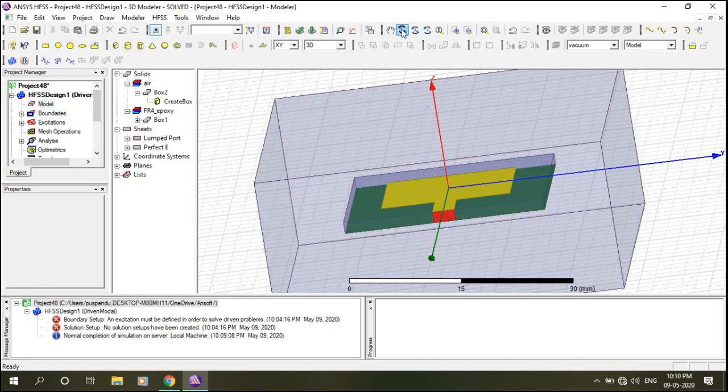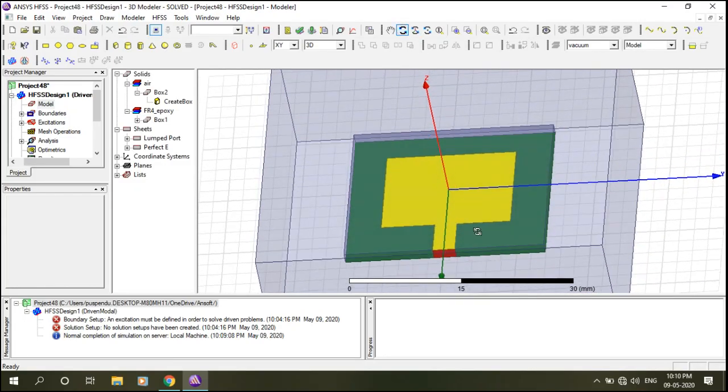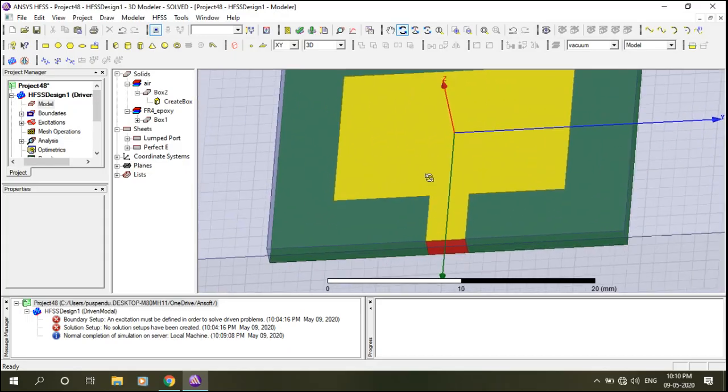Here we have given the microstrip line feeding. For microstrip line feeding, inset feeding is required for impedance matching. Inset feeding is nothing but you have to insert this feed line inside this patch. So for that you have to cut from here and here. You have to draw a small rectangle here and here, then cut out these rectangles from this patch for impedance matching purpose.